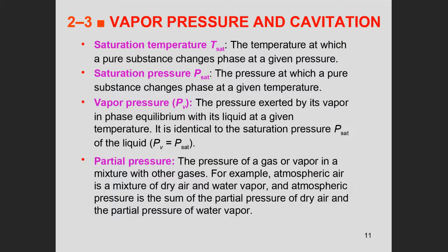Now, we are still talking about properties, and here we'll talk about vapor pressure. Gentlemen, you remember in your thermodynamics you have the PV diagram and the TV diagram, right? And you learned that for every temperature there is a specific pressure called the saturation pressure.